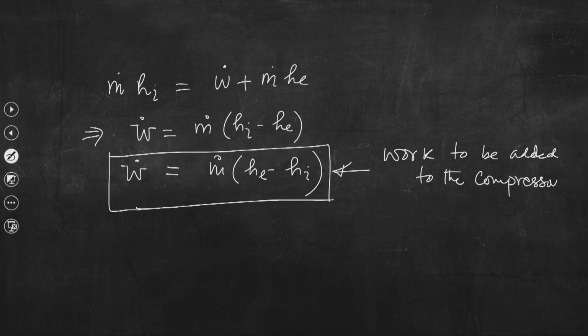Addition of energy in the form of work, okay. And now we can write, if we assume the specific heat of air remains constant, then we can write W dot, and this is not the actual work. So, this is the ideal work, that is equal to m dot into Cp into T naught minus Ti,